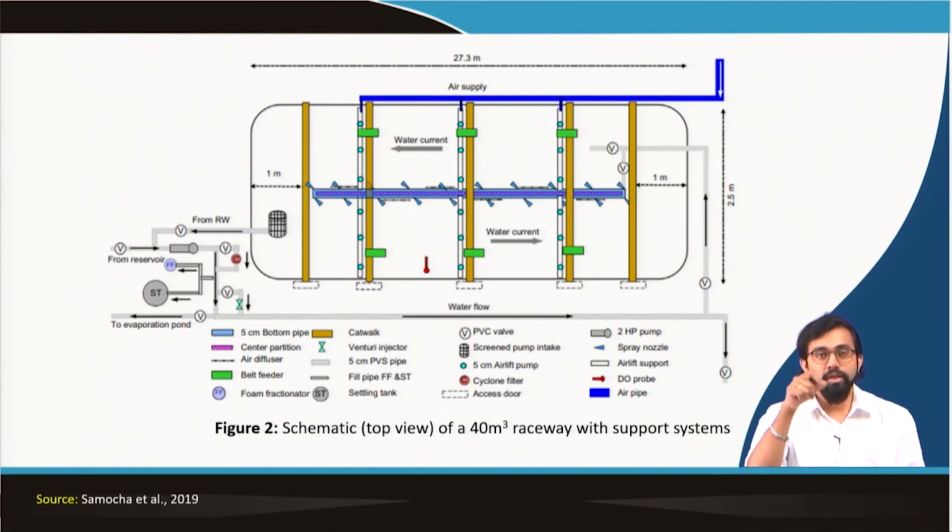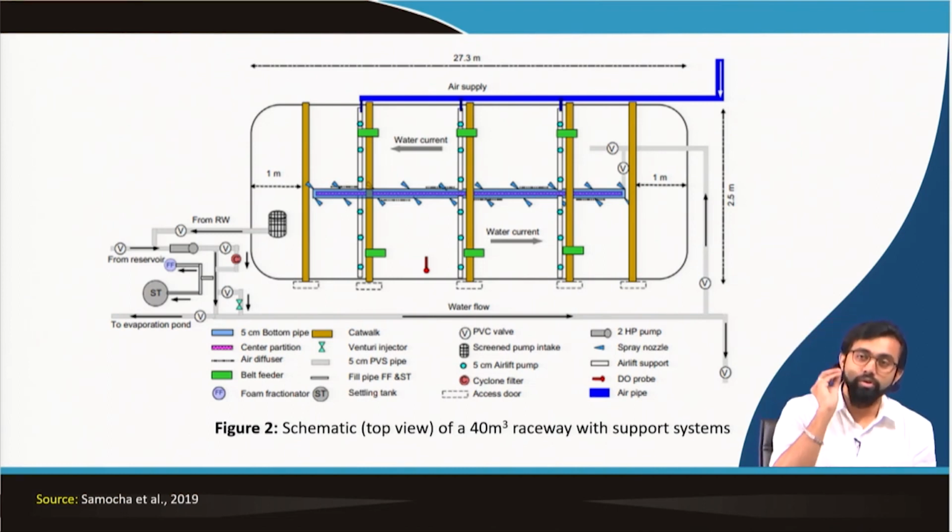And then after the oxygenation is happening and the treatment is done, water goes again through the Venturi injector and the normal line, going back to the pond. Some portion of it we also take out depending upon the treatment requirement. Sometimes we add some additional biofilters. Biofilters are actually for the smaller size raceways. For bigger size raceways, we do not need biofilters in general. Everything that I am saying here depends on the design and specific requirement of your pond.